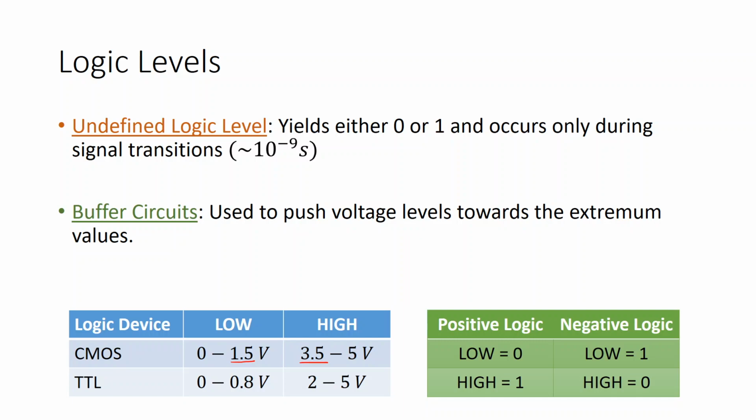However, in the normal operation of transistors, when we operate them as switches, they are either in the low range or in the high range at steady state. Between 1.5 and 3.5 is the transition state. Suppose a transistor is being turned on from an off state; obviously it will go through all these voltages.